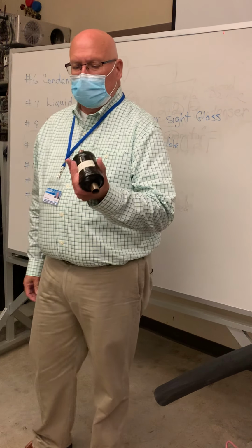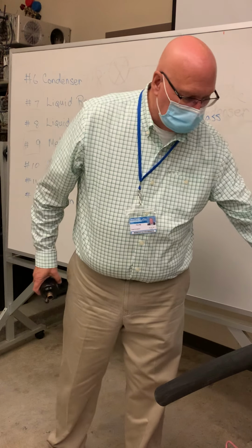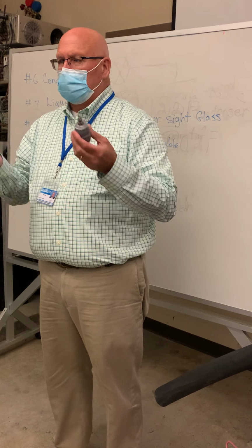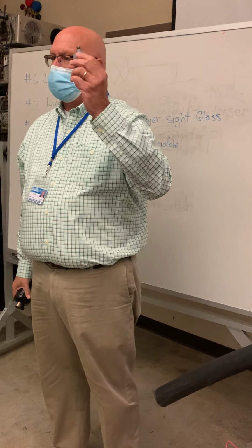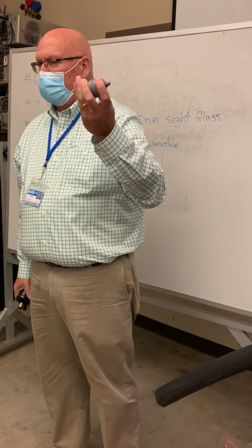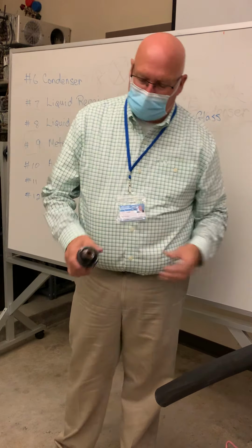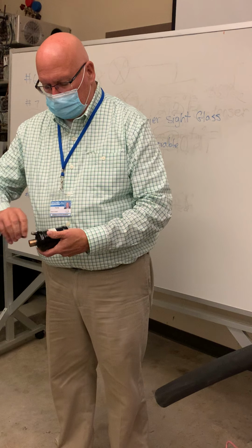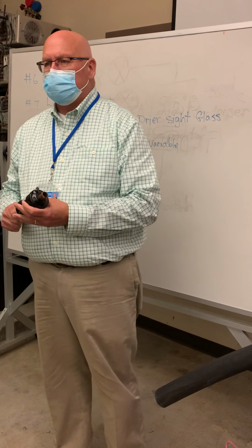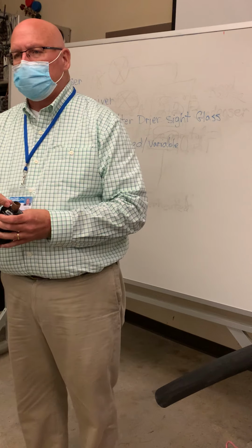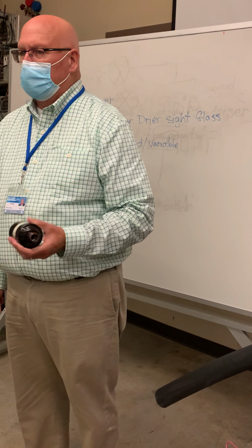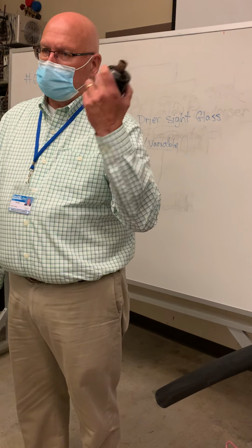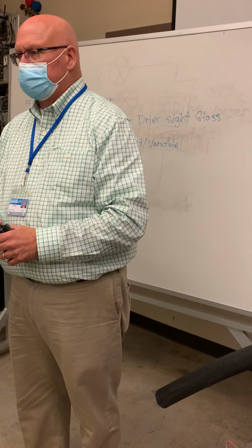The suction line filter dryer looks different than the liquid line one, because one's bigger, one's smaller. This one, remember, we check with temperature to see if it's at capacity. This, we check with gauges. So you look at the gauge pressure going in, and then you measure the gauge pressure going out. And if you get more than 3 psig, this is at its capacity, no longer any good.